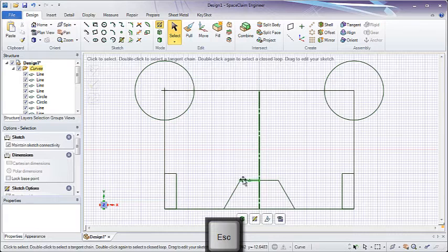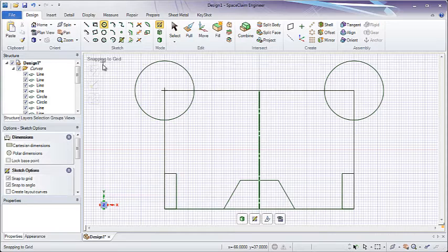So now that I've added these sketches in the center, what I'll want to do is add one more circle here. Now remember, if you click circle, you can click the Cartesian dimension or polar dimension to set where you're starting from, but a nice shortcut for this is to tap the Shift key.